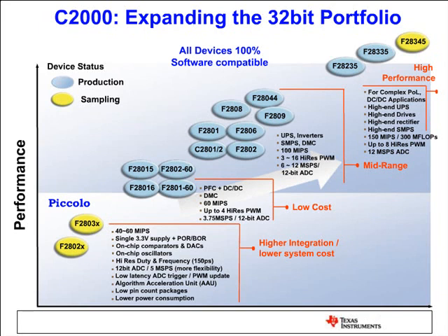And Piccolo has a 12-bit ADC again, and it's quite fast. As I'm going to talk about later, it can sense the current through shunt resistors on the three-phase inverters, which is a very important feature for motor control applications. And it has an on-chip CLA, which is a control law accelerator. What you can do, basically, is develop CLA code and run the control loop algorithms on the CLA, and the rest of the operation can be handled by the 28x CPU.